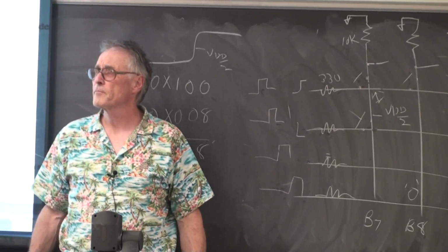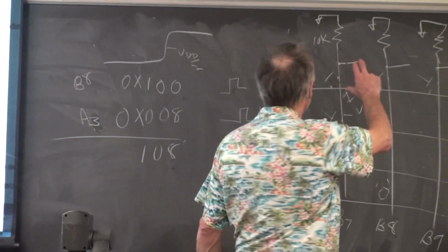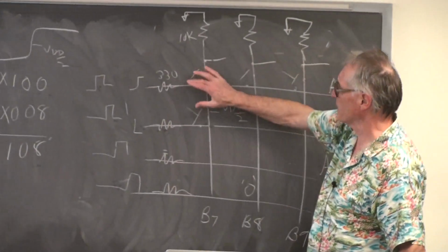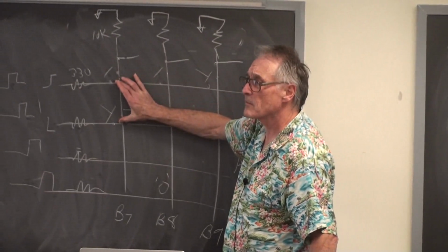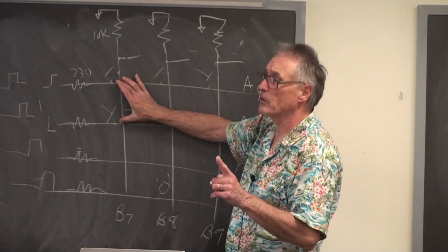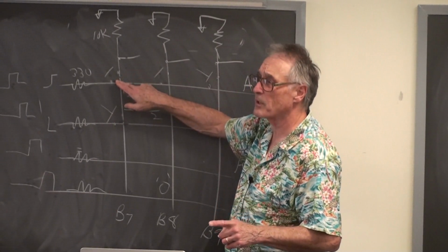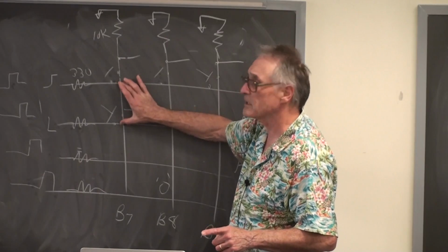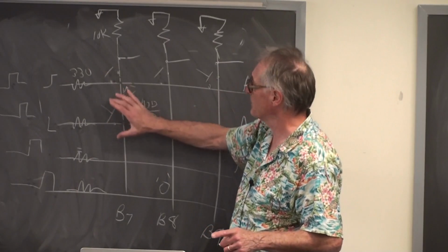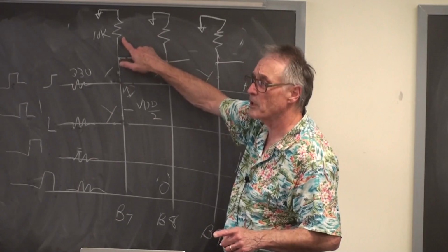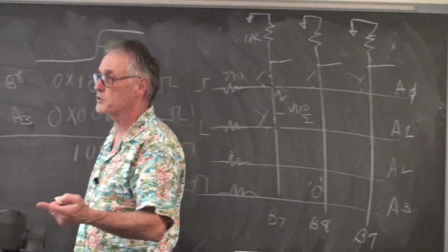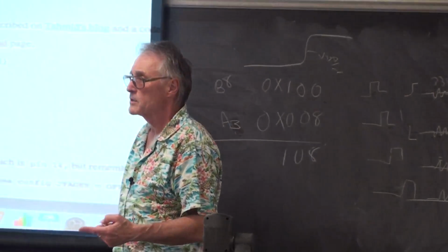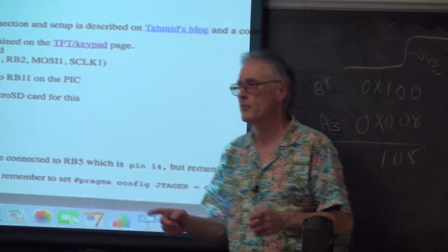Actually, does it? If you float all three and leave this one connected, and you press these two buttons, that will not detect a fault. All it will do is say you pressed button 1. So it won't detect the fault. Whereas if you leave them all connected, and you have enough current flow through here, you'll get a 0 and it won't respond because you'll have a fault condition. You'll have 2 buttons pushed at the same time. So it might actually be a little better to have them driven all as outputs.